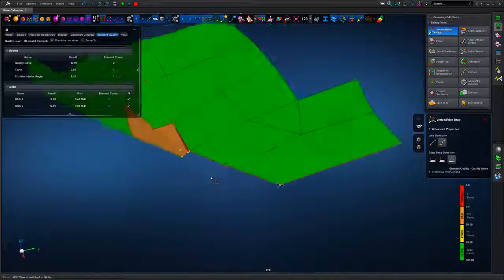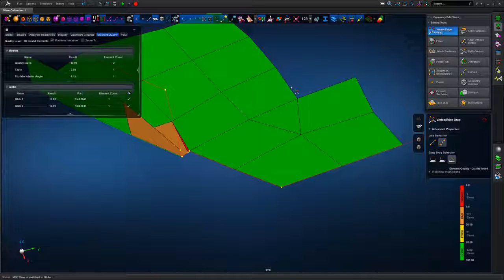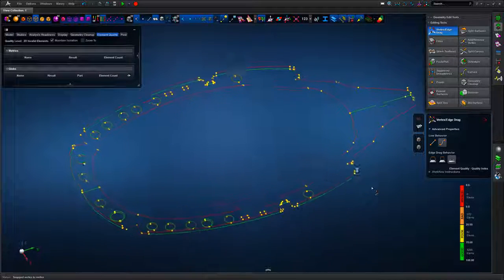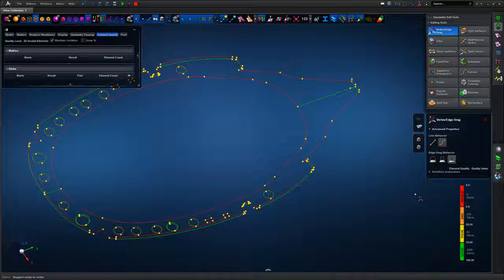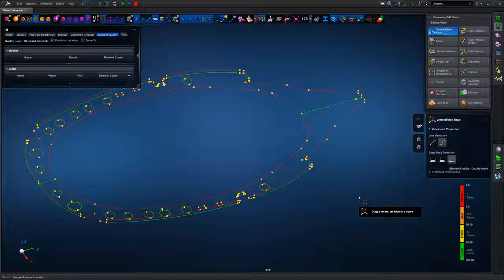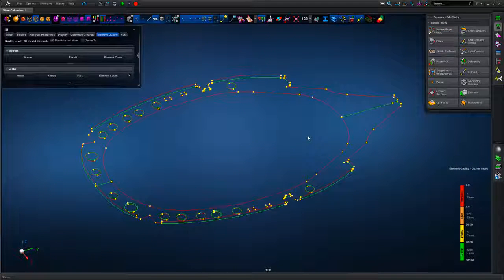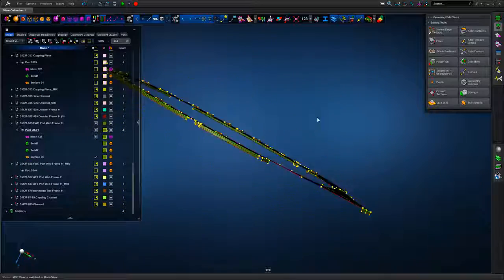We can see that the mid-surfacing has just created a couple of extra vertices where the original fillets would have sat. If you remember, they were there before we defeatured, so it's just left some vertices behind. So we do that defeaturing operation. On the left hand side, the model browser tree shows that in terms of element quality we now have good, we have no invalid elements anywhere. We have some poor and bad elements, and we could take some time to understand where they are, but in terms of our